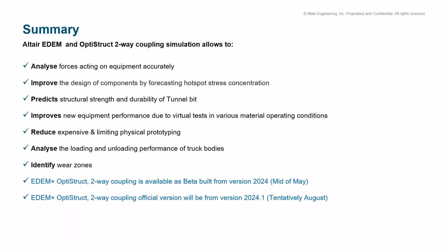There are a couple of questions I can answer. It's about the EDEM simulation size. Remember that the EDEM simulation size will depend on your particle size and also on the number of particles that you have. The smaller the particle size and the larger the number, the more contacts you will have, hence large simulation files. For recommendations on what you can do to speed up your simulation, see the community. But basically, these two factors, number of particles and size, are key in your simulation.